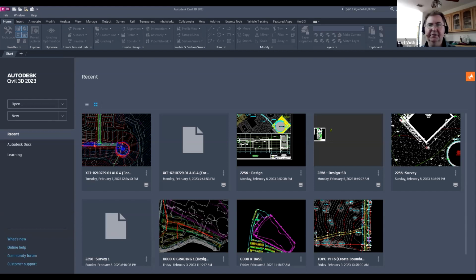So everything in road E, I need to go over. Road G, I'm going to keep in there. I'm going to keep my intersection functionality for road G, but F, I'm going to send over to that one and that one as well. And that connected alignment down there at the bottom.